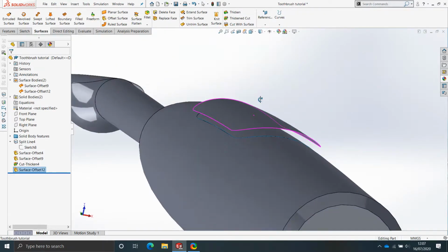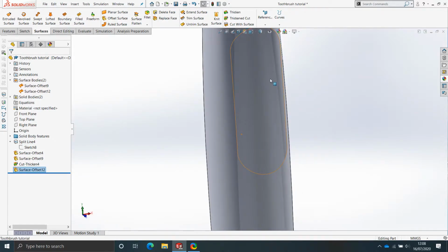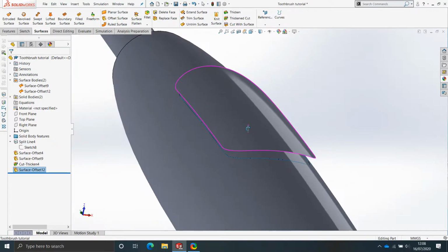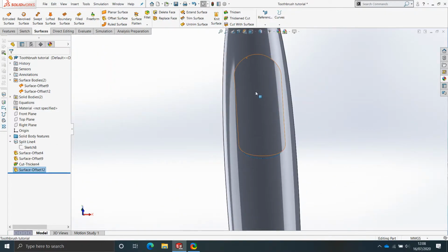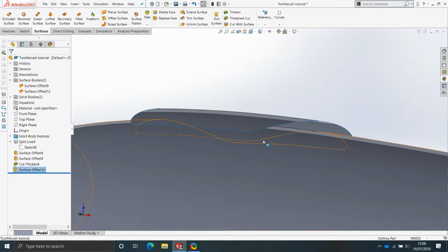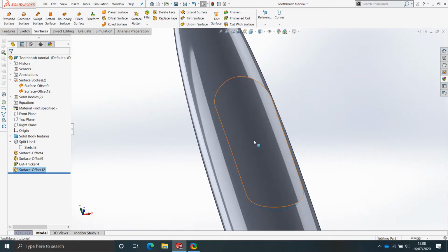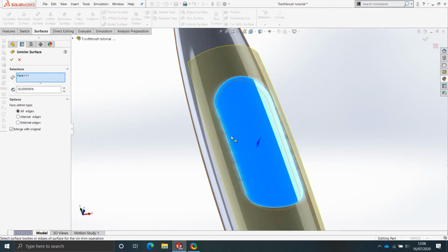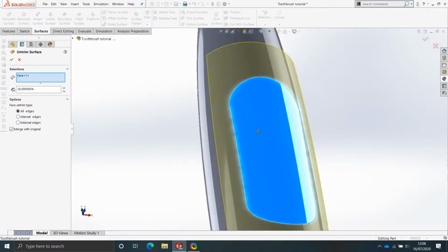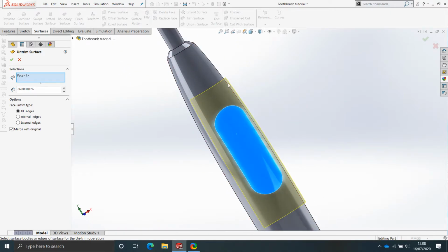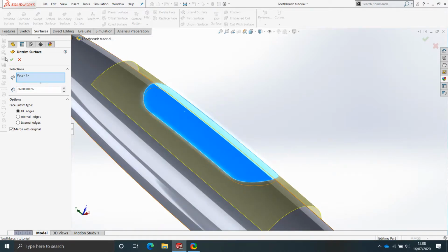Now when I sketch onto this, I'm planning on simply doing an offset of this shape, but you could in theory sketch any shape onto here and then do a surface loft or a boundary surface from this edge to that shape. And I'd suggest a good step first is to take this and to untrim this sheet. So we can use this command called untrim surface here, and what this does is it takes this surface and it basically extends all its edges out to how it would imagine it to be before it is either split or trimmed. So we can use that.